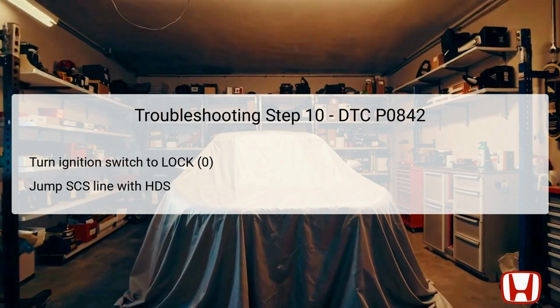necessary actions. Disconnect the PCM connector B, which typically consists of 44 pins. This action isolates the PCM, or powertrain control module, from the system. Focus on checking for continuity between PCM connector terminal B8 and body ground using an appropriate multimeter. The wire associated with terminal B8 is usually coded as OP2SW, blue-yellow. Ensuring continuity without breaks or shorts is essential for appropriate functioning of various transmission systems.